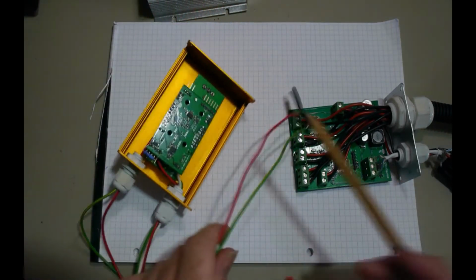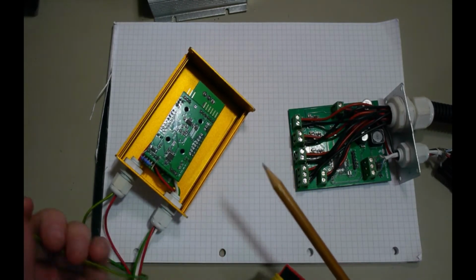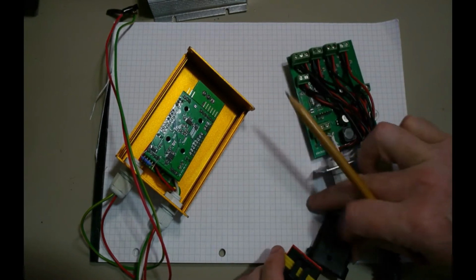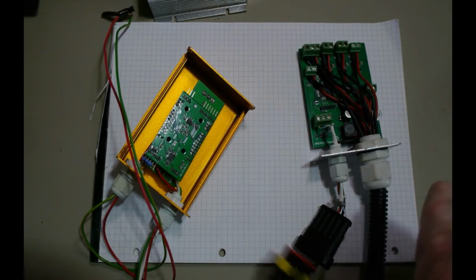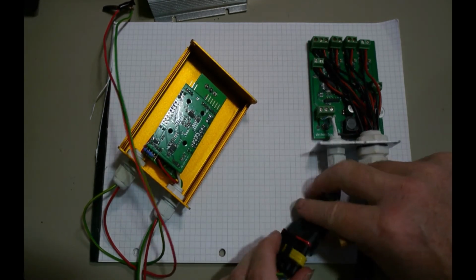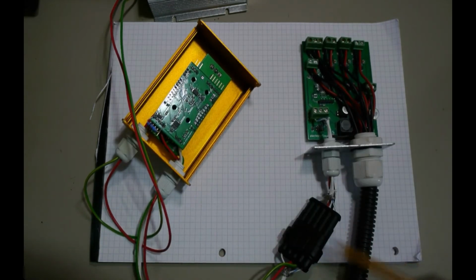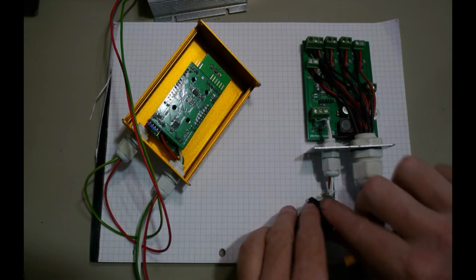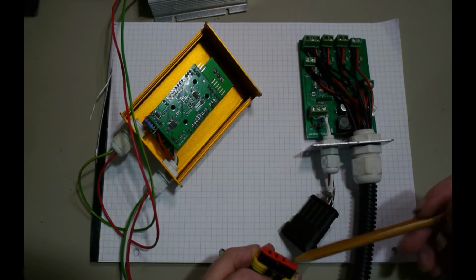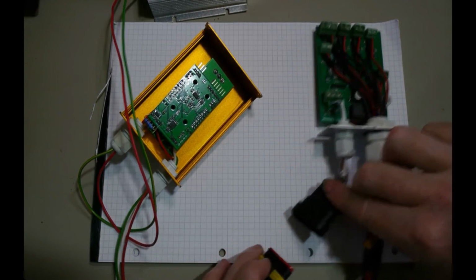So power comes in from the tractor. Obviously that's maybe not the best connector that could have been, and then power is transmitted down along with the CAN high and CAN low through a 5-pin connector. Now obviously I can make a cable, any length of cable within the limits of the CAN protocol specification, which I think is 30 meters, but we're not going to use 30 meters. I can make any length of cable with a 5-pin connector on each side and just insert it into this connection.